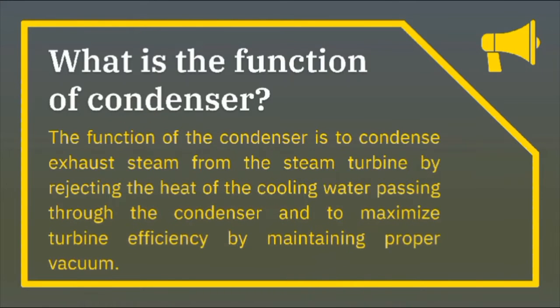The function of the condenser is to condense exhaust steam from the steam turbine by rejecting the heat of vaporization to the cooling water passing through the condenser, and to maximize turbine efficiency by maintaining proper vacuum. Once the steam has passed through the turbine, it enters the condenser where heat is removed until it condenses back into liquid water.